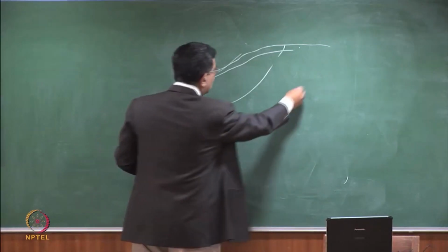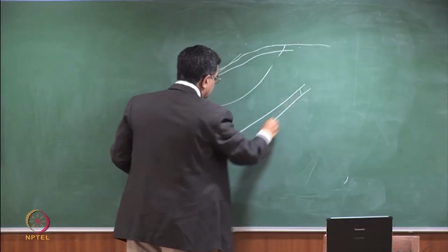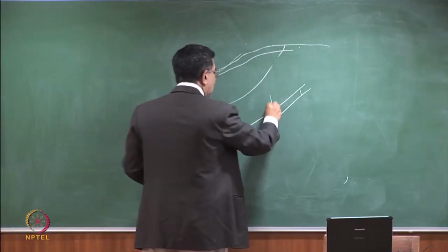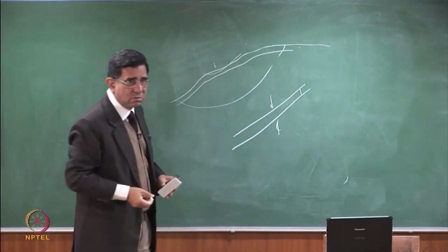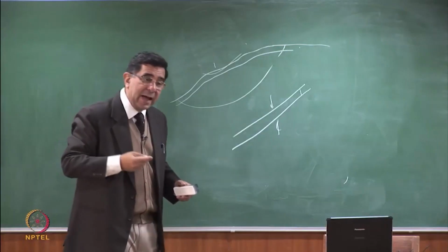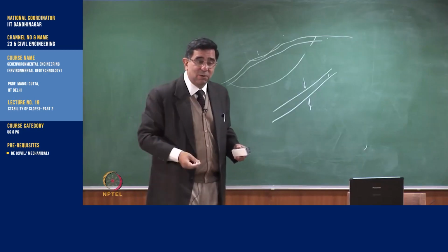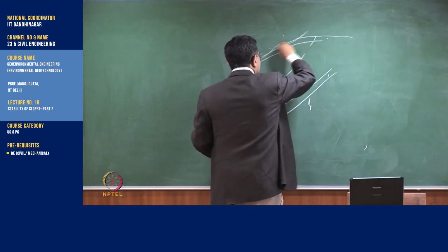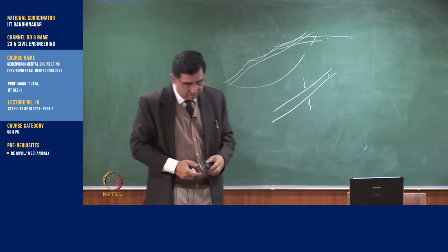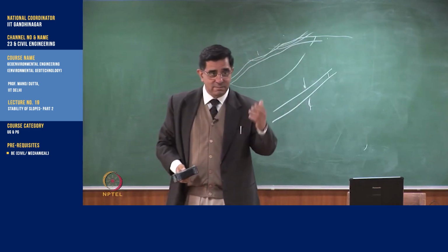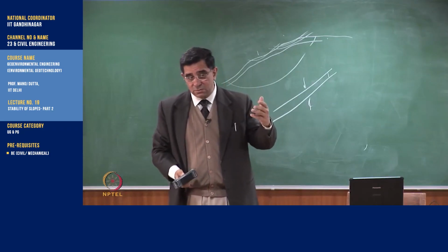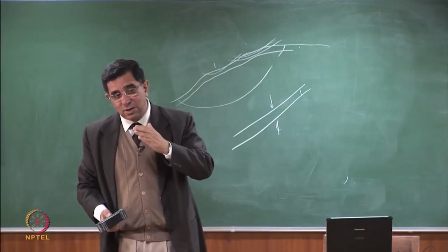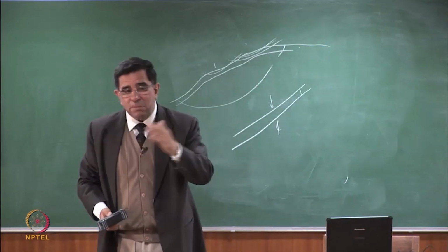So therefore, when you do infinite slope analysis, you are always presuming a failure surface parallel to the outer slope, and this thickness is very small. So you'll say, sir, where is the failure surface parallel to the outer slope? It's a circular slip surface. I keep on increasing my radius of the circle. What happens? I make my radius infinite. Is a circle of an infinite radius a straight line? So in your software, unless they have a boundary condition that you can't take, you'll find that for infinite slopes, your circles will become very flat. They'll become almost parallel to the outer slope.